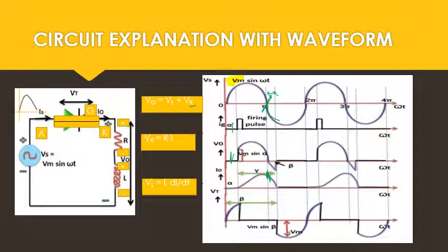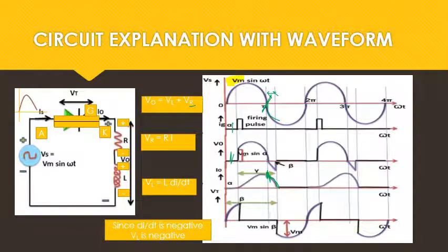And then the inductor starts to reduce or release its current through the I out. Now let us see this. What is VL? VL is L times di by dt. Here the current was initially, let me say, some 10 milliamperes or so. It started to reduce to 0. So this is negative, so you will get minus di by dt. Now if I substitute minus di by dt in this region, it is going to be minus VL.